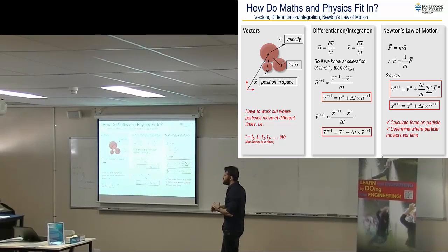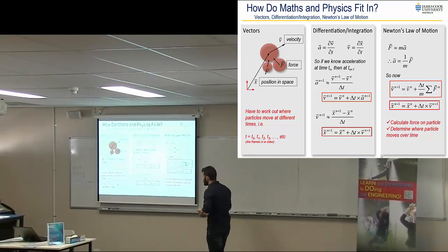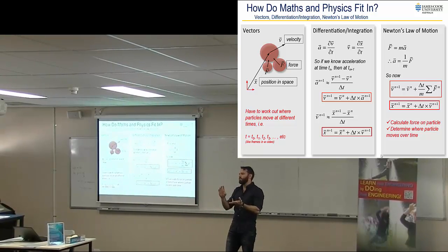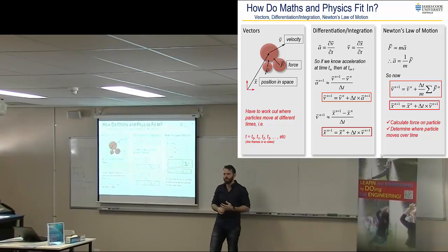And in terms of that code I showed you before, that's basically what the students are doing. So particle overlap, and the same thing with boundaries. If a particle overlaps with a boundary, it just calculates a force based on a spring relationship. Now for the more complicated stuff, you'll have friction, and you'll have cohesion, and you can potentially have any number of other things like drag and all of that kind of physics that you would then calculate additional forces for on each one of those particles, and that all gets calculated there every time step.